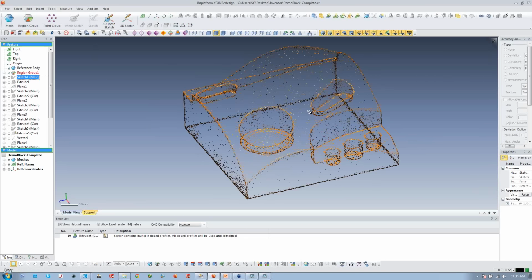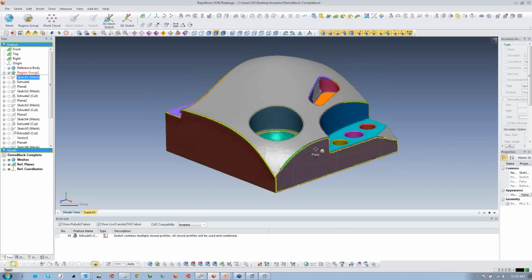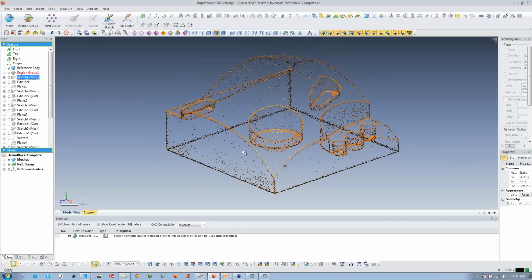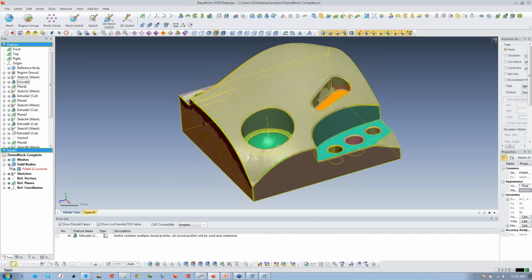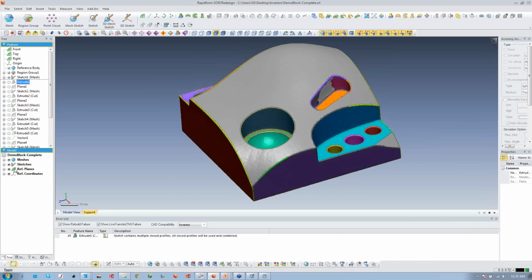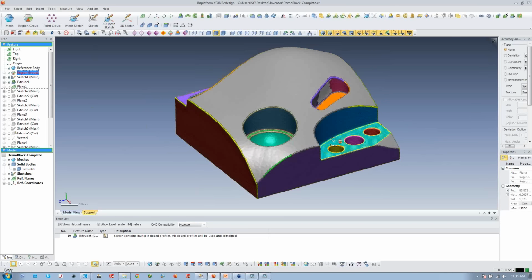Quick modeling is going to need from us region groups in order to create or understand the solid. So the quick modeling workflow relies upon our wizards, which are up here. In order to model this as an extrude cut, if I roll back here and roll forward, let's say I'd like to model an extrude cut right here. I'm going to need to have a bottom and a side in order to make that.